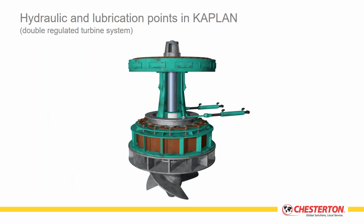Let's have a look at a typical Kaplan turbine. This turbine is a double regulated turbine system, meaning double regulating, that we regulate the position of the wicket gates, and then we harmonize the position of the runner blades to the wicket gate positions.